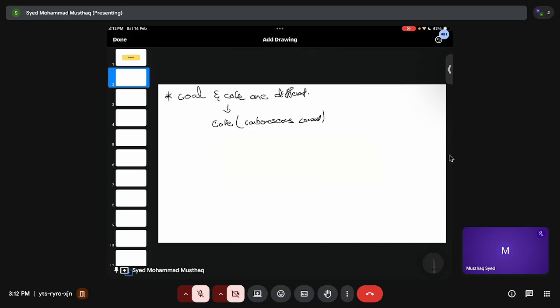Now how do we arrive at coke, right? What we do is we take caking coal, so we make cakes. Nothing but you form a compact with pitch or tar or anything, or water, moisture also, we can take water also, to make a green compact, and then you heat it in the absence of air, right? So that is what the coking process is.